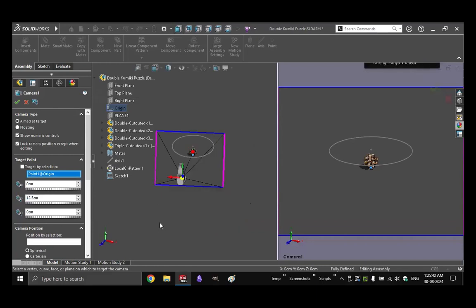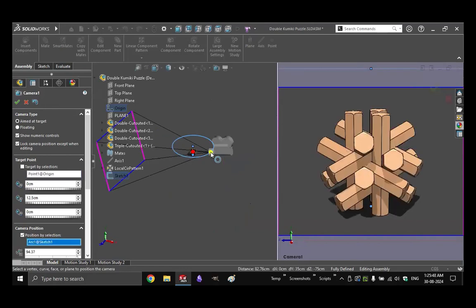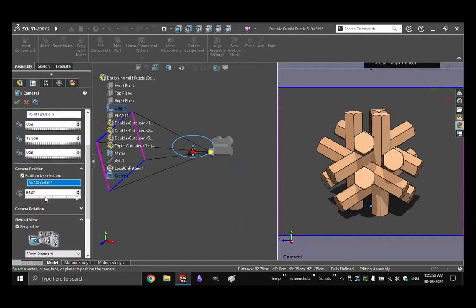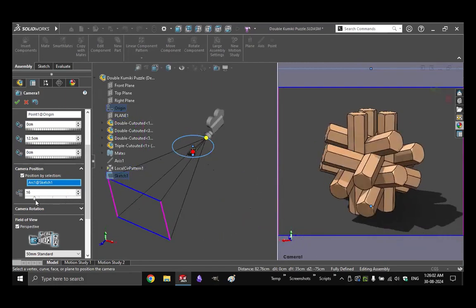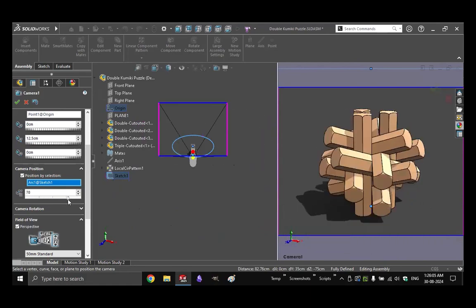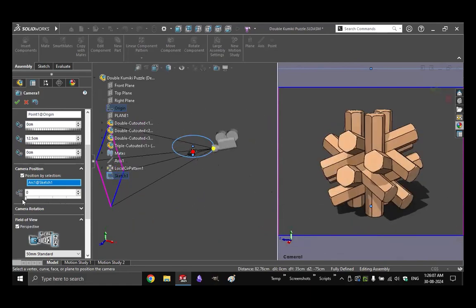And when it comes to the camera position, this is the cool one. So in this case, I'm just gonna select this circle. And now this is the path for my camera. And since I've got this path, now I've got this cool slider over here. So look at this camera over here, okay? And tell me what happens when I move the slider around. Look at that. Cool. So what is happening is the camera is actually going along that slider from one end all the way to the other.